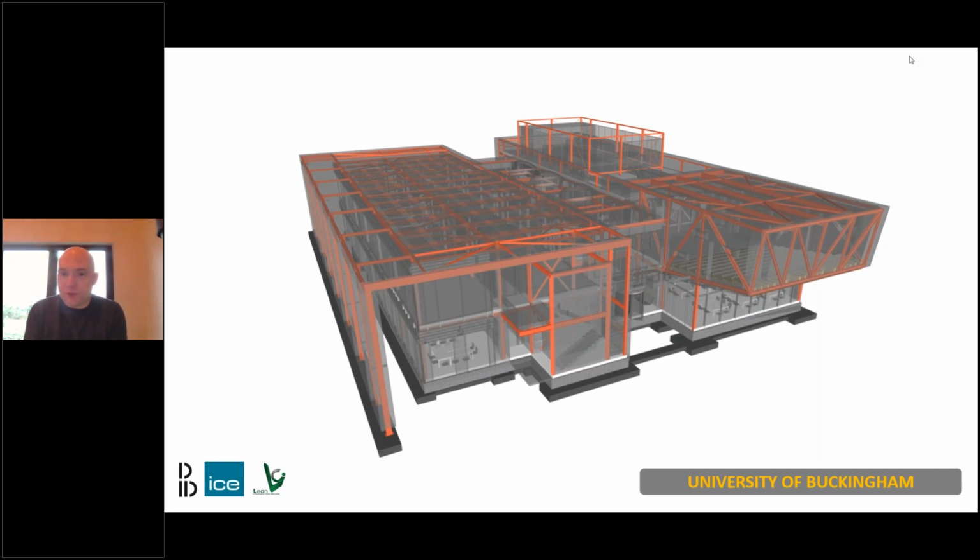So what we ended up doing is we said, well, let's use the form of the building. Let's use that big depth of the lecture theatre to create some very efficient structures. So what we did is we provided steel trusses within the cheeks and the face of the lecture theatre there. So we knew that we could achieve the big cantilever span there by utilising a full depth truss. The full depth truss became very, very efficient. The diagonals that we put in there would only have been the columns that would have gone in the ground anyway. But by using a truss with the top and bottom chord, it meant that we could reduce the size of the steel beams associated with the top and bottom chord of that structure.